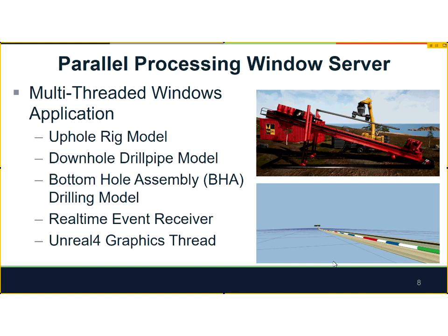out. This is the carriage. It basically slides in and allows them to bring in new pipes, and it'll connect on the spindle up top and connect to the drill string down below. And this is the deckhand gripper that I described, that is basically queuing and grabbing pipes off the stack, bringing them into the system as the driller is putting pipes in. When they're pulling pipes out, it'll grab the pipe and stack it.